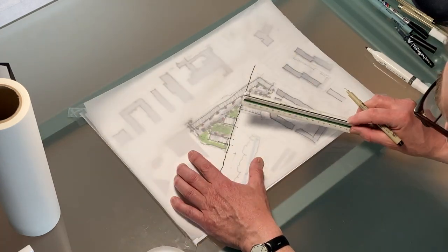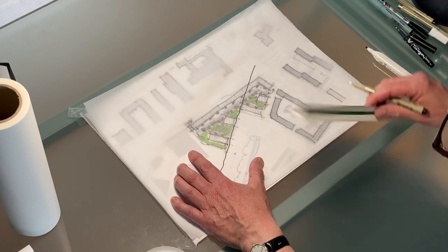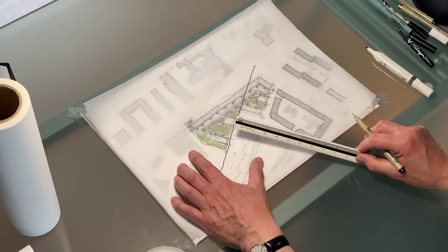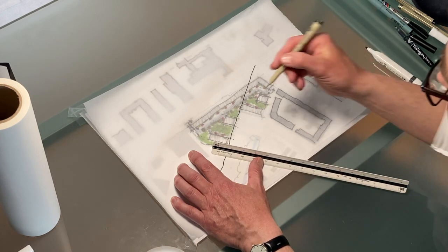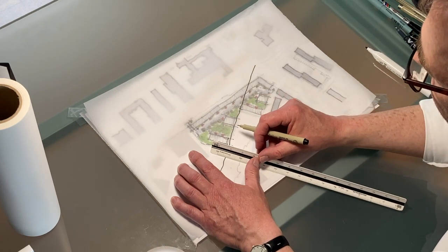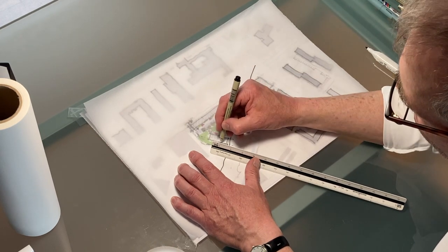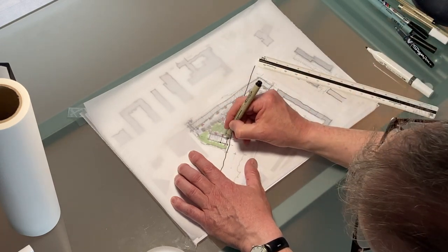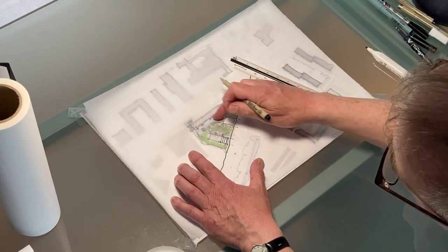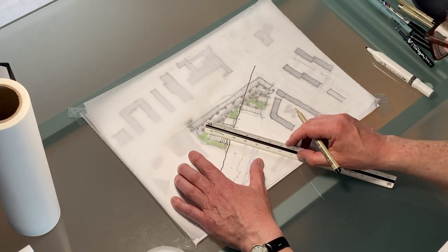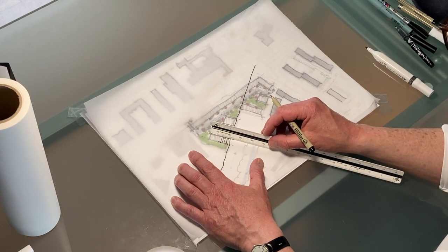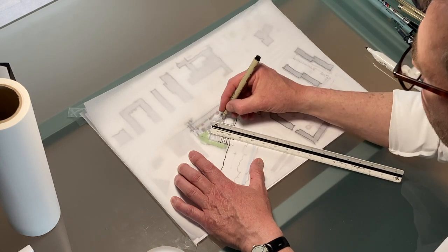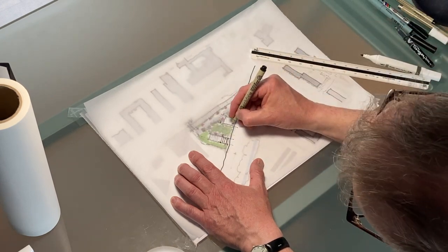And let's assume that this is like a 5-story building, and we can roughly put a story to 3 meters. So at scale 1 to 1,000, 5 stories then would be 15 millimeters, and I would take out my scale ruler here, and that would go up to here somehow, and then I can just add some floors, and maybe this should be then a tower of, I don't know, let's say 8 stories, so that would be 24 meters, and I could add in the stories